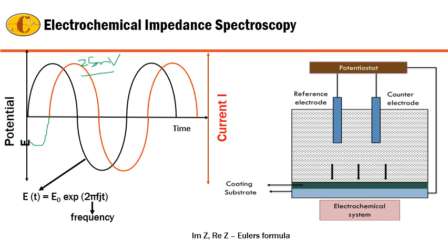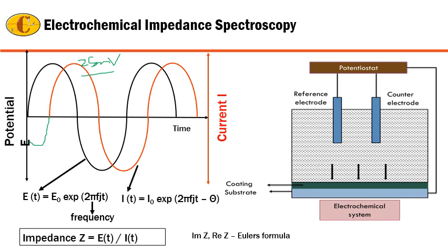So with respect to the first point, you have a certain current measurement, and because you are using an alternating current, you have values of frequency. So typically it's not done at a single frequency, it is done at a very high frequency first, then medium frequency, and then very low frequency. The impedance in this case is calculated because it is alternating current. We do not really refer to it as resistance, it is impedance, and it is calculated from the ratio of the voltage to this current.